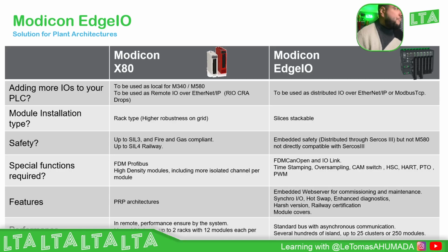There's no need to remove the power supply. For safety, there is a lot more safety on the X80. So if you want a safety application for different IOs, then move to the X80. Not the Modicon EdgeIO, because most of the safety functionalities are based on the Sercos part, and the EdgeIO doesn't support Sercos, so it's not really compatible.